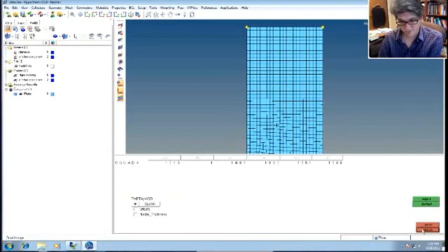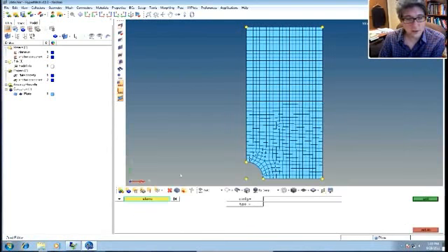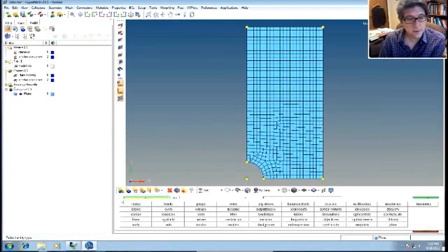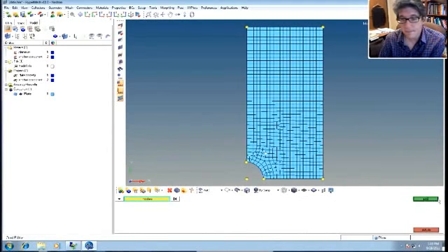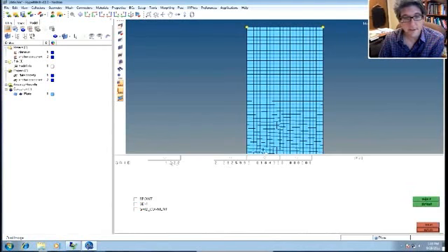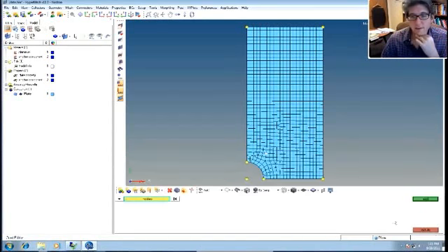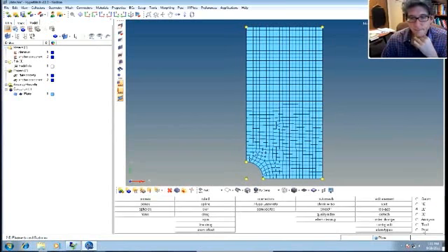You can edit it, but it's not really something you practically do, but you can at least look at that. Likewise, you can also look at nodes if you want to. Pick a node. There's a node. Let's edit that. And there it gives you the coordinates and all that sort of stuff. And you can go back in and add coordinate, alternate coordinate IDs and all that sort of stuff if you wanted to. Okay?